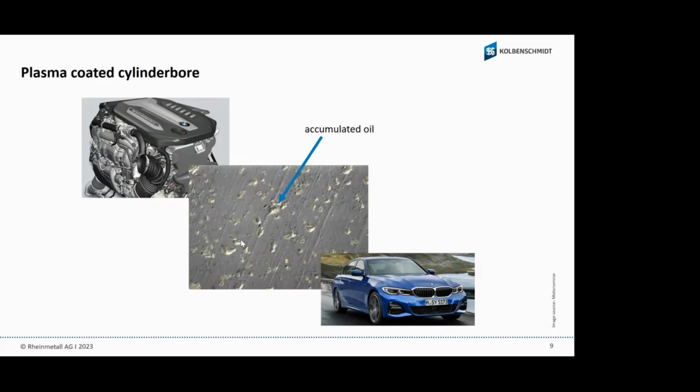Altogether, the tension of the piston ring, the oil viscosity and how thick the oil film is, and also the roughness of the surface, all three components give this tribology situation. And when one is not in the right condition, then we have a problem. And then we can speak about oil consumption. This can be the result.